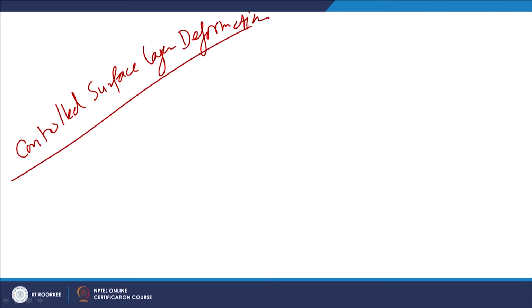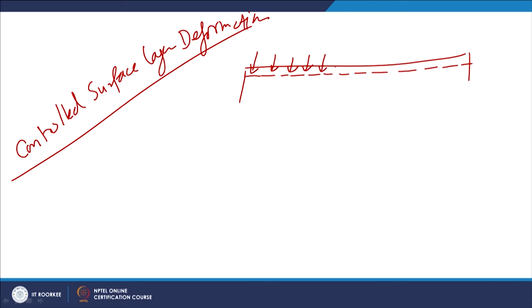So, the basic, broader idea in this approach is that the surface whose properties are to be improved will be deformed plastically up to the required depth using the controlled application of stresses. So, this surface layer is deformed plastically, and plastic deformation will lead to an increase in hardness for increasing the wear resistance. This is the idea, but how this improvement in properties takes place and what are the other effects related with this approach, about that we will talk.